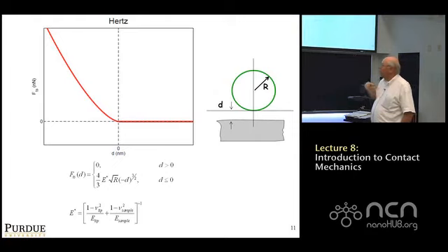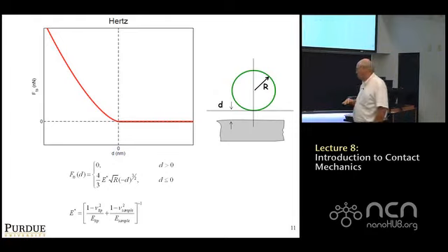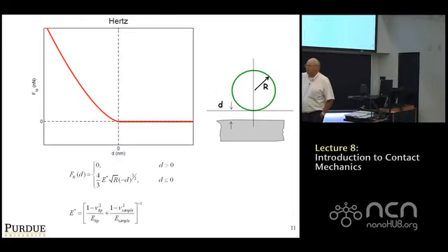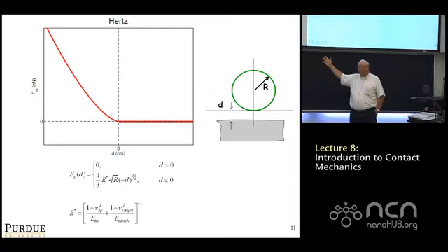So, in the Hertz model, no tip substrate forces until the tip is in contact with the substrate. That's the characteristic feature of Hertz, okay? And if you think you have very hard substrates and very hard tips, then maybe the Hertz model is appropriate for your situation.